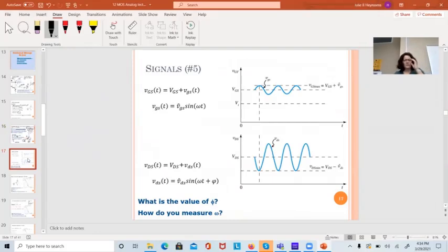Okay, so these are typical signals, and you get to plot these in 380. I have little v, big G, big S. It equals a DC, which is a time varying signal. It equals a DC value, not a function of time, big V, big G, big S, plus little v, little g, little s. And if we plot that, the DC value is the average value that you would see on your oscilloscope, whereas the signal is kind of small right there. And same thing for VDS, there's a DC level and there is a larger AC component.